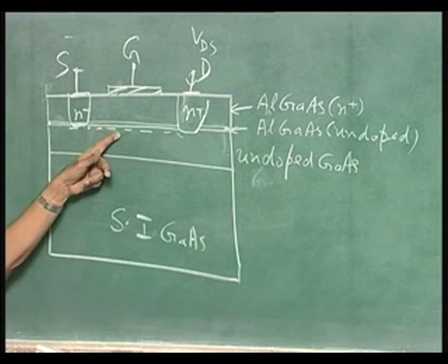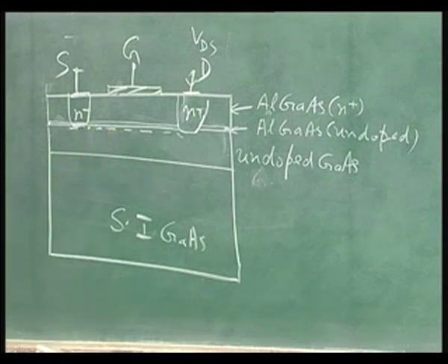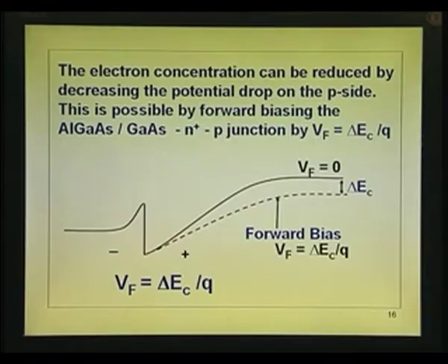So, this particular charge you can reduce, because that is the notch that we have shown here. Okay. That is the notch. Aluminum gallium arsenide, and this is a situation where there is no gate. Okay. Just like this, and that is a variation. Forward bias voltage is equal to 0, thermal equilibrium situation, and electrons are locked up here, of course, with E1 and E2 energy. They are not just staying there as a gas, though you call it electron gas, 2D electron gas, it is quantized electrons.